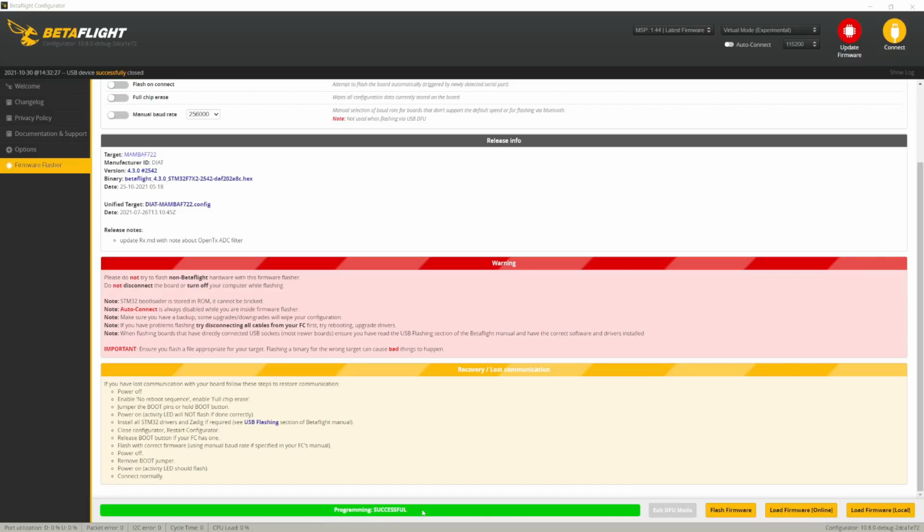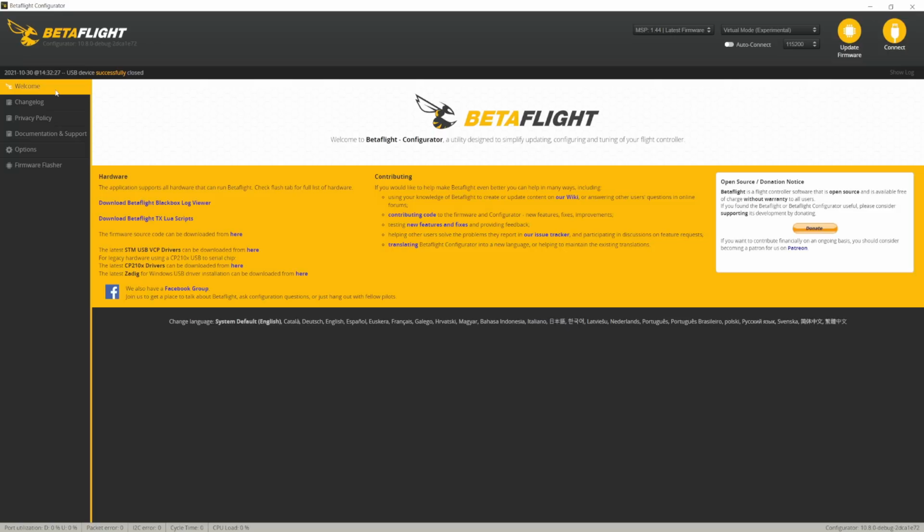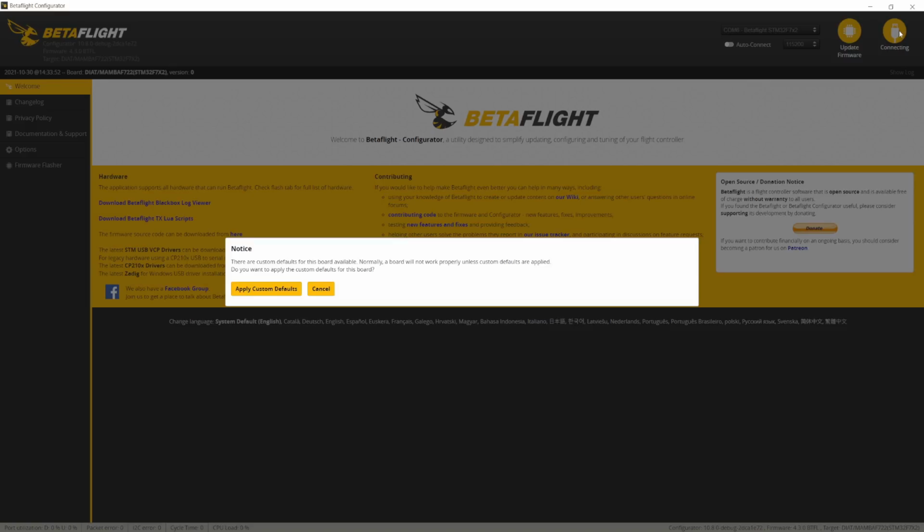If something goes wrong, you may need to reinstall your drivers using AOS RC driver fixer, and I'll put a link to that down in the video description. Now go back to the welcome screen, unplug and re-plug in your flight controller. It should be detected and you can click connect.